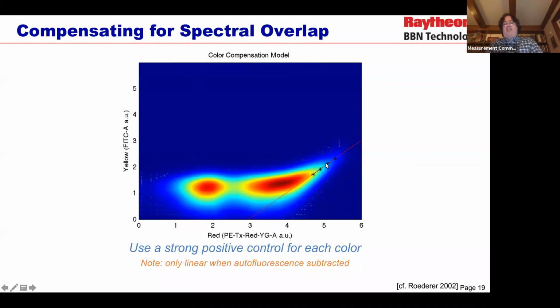Once you have these models, it turns out that because this is a purely linear relationship, if you make a model of each of these individual pairs, you get a matrix, which you can then just divide versus the measurements you get, and you unentangle those measurements and are able to compensate. So as long as it's fairly low, like I said, about 3% or less, you can remove pretty much everything quite cleanly.